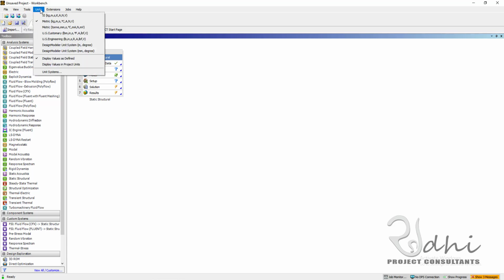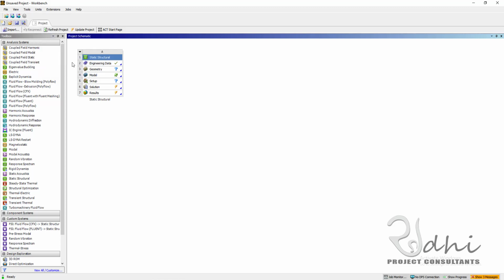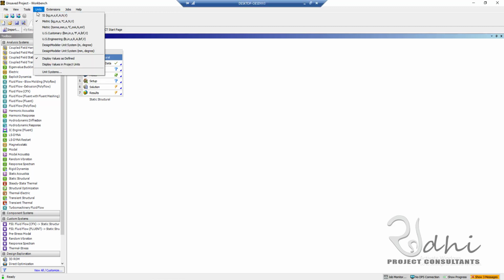Okay, then the next important thing, it is actually a blessing in ANSYS, because ANSYS has units. So you can give your own units, because in most other software, if you go to Abaqus, I'm not degrading Abaqus, I'm not saying Abaqus is a bad software, it's not like that. It is also a good software, but one of the troubles it creates is a lack of units. So in Abaqus you must know the units, and you must give the properties in consistent units, otherwise it will create a lot of problems. But in ANSYS they actually gave us the units, so you can give the results in particular units, the available units.